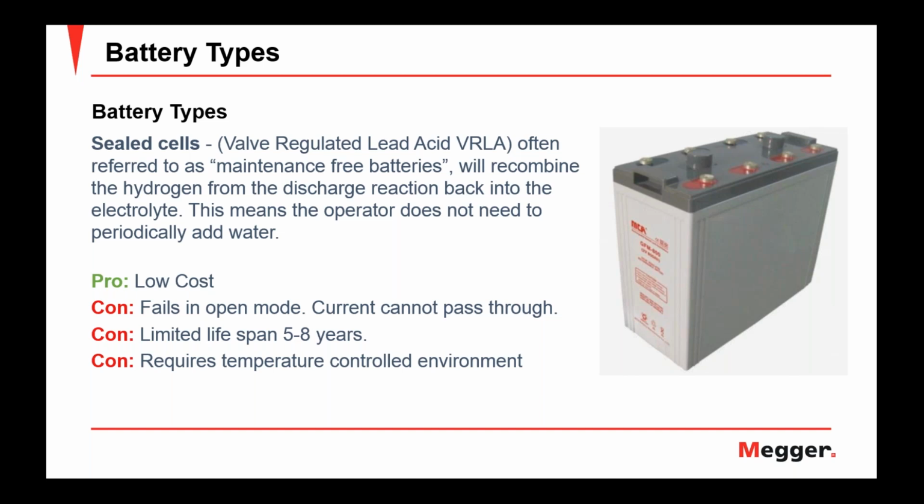Now, it doesn't mean they're open. It just means that current cannot readily pass through them. So if these are to be used in critical applications, it's recommended to use parallel strings so that if one battery fails, you can still get current through the parallel string.